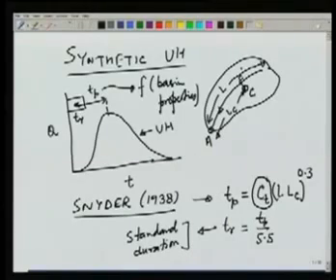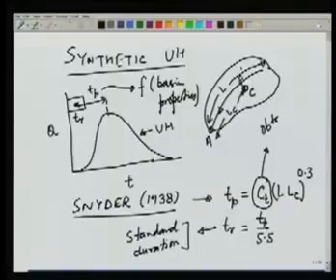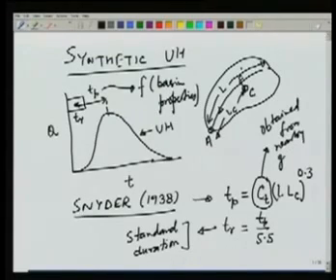Now, in general, we may not want to derive a unit hydrograph of duration TR, and we may have the value of CT typically is obtained from a gauged catchment, which is similar to the catchment under consideration. So CT is obtained from nearby gauged catchment or gauged area.